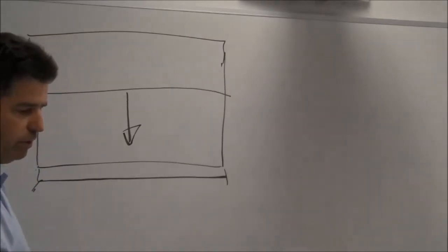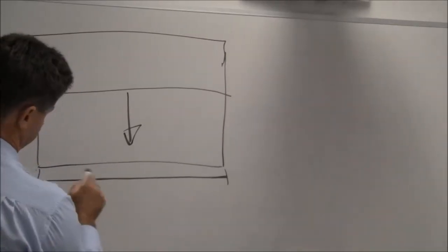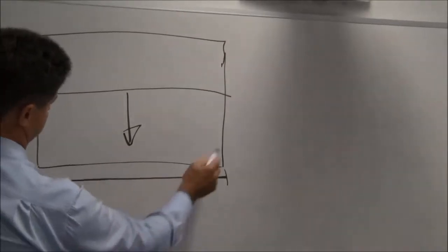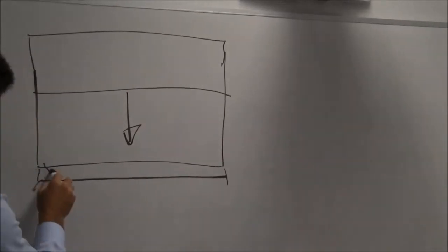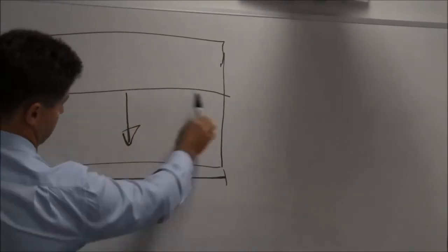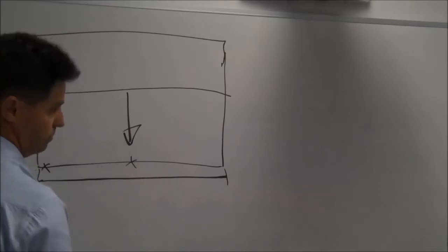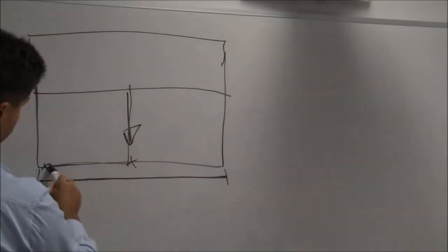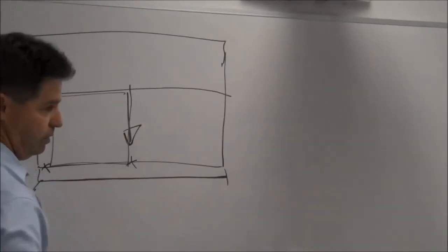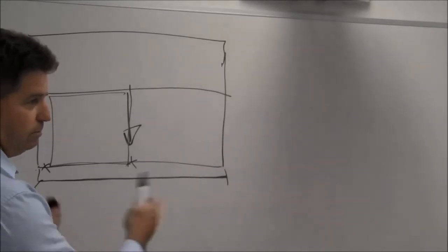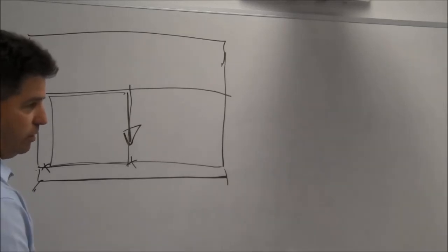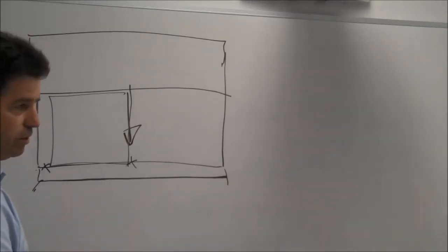The problem with doing that is it depends where, especially in a box gutter, your outlets are located. If that was our total roof and we put the outlet at this end, then the size of the box gutter is determined by that entire area. But if we put it in the centre, the box gutter's sized just on half that space, no matter how many downpipes you put in. I know a lot of guys just divide it by 4, but all you're doing is increasing the size of the gutter for no real reason, especially if you're stuck with dimensions.